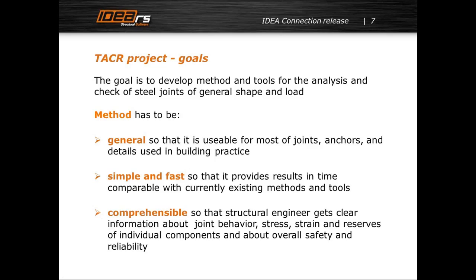So it means that the structural engineer gets the information what is happening in the connection, where the high stresses are, how the bolts are loaded, etc. We think that the current methods are not so explanatory, that users only fill in some formulas and get some results, but the real understanding of what is the weakest part of the connection is not there.